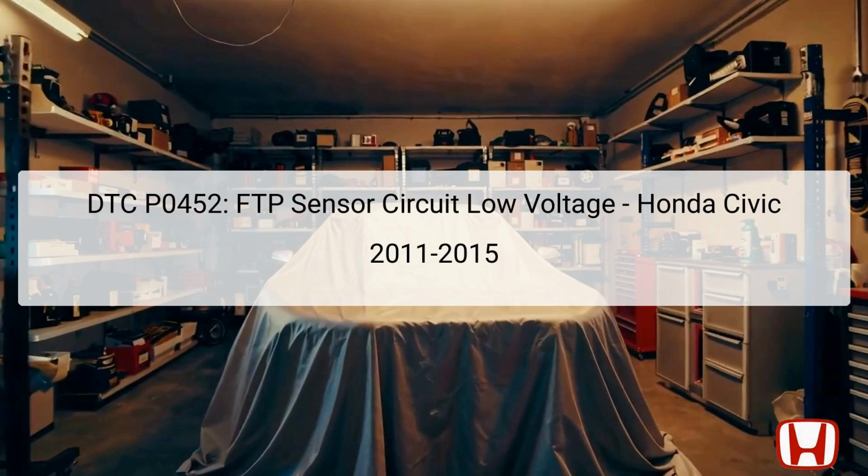DTC P0452 indicates an issue in the FTP, fuel tank pressure sensor circuit, with low voltage readings. This code suggests that the voltage signal from the FTP sensor is below the expected threshold, typically around 0.3 volts or less. The FTP sensor is a critical component of the onboard evaporative emission control system. It monitors the fuel tank vapor pressure to prevent fuel vapors from escaping into the atmosphere.